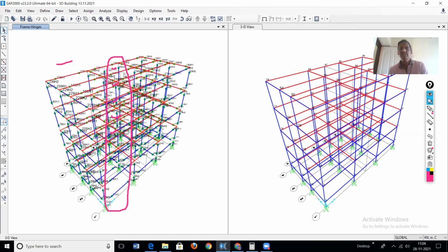by using that approach. For the shear wall, you can either assign the nonlinearity using the wide column approach, which is called the lumped plasticity approach, or using a shell element, which is called the distributed plasticity approach. Researchers have studied these cases, and the results show that both options give results very close to each other. My personal suggestion is that whenever shear wall nonlinearity comes up, you always go for the wide column approach.